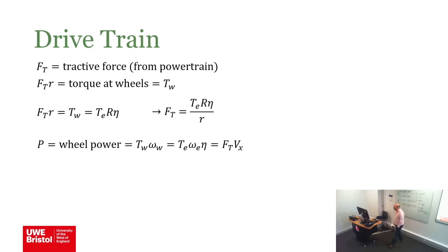If you can work out the drag on a car, and if you know what power the engine's generating, you can actually work out what its top speed could be from these equations. Because if you know the power of the engine, you can work out what this is, and you know the speed at which the engine's going. You can also work out what dx is, because you'll know what this term is if you know what all the drag force is.